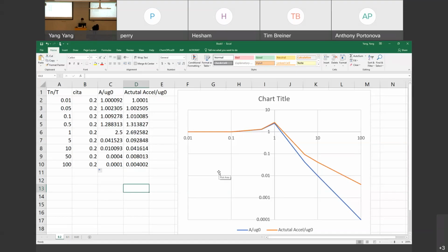So any questions up to here? Is everybody able to construct the response spectrum? If the earthquake record is given to you, at least for one selected damping ratio, and if I give you a set of different T values, you should be able to do that.